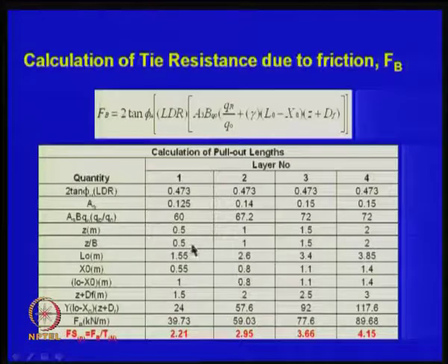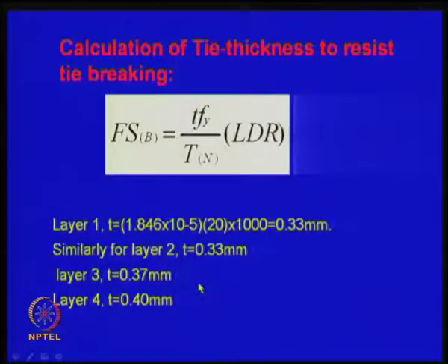So, you have to reduce it somewhat. Anyhow we will see that, but you can increase the footing size, like say B equal to 2 meters or 1.5 meters, and try to do some more modifications. We will see how modifications could be done, but this gives a basic idea that you can calculate the tensile force required and also the pull out resistance and other factors.